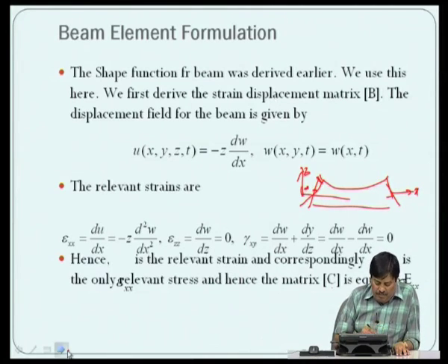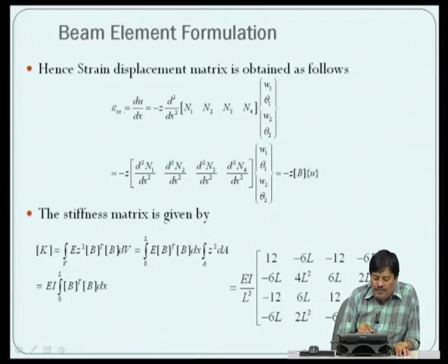Here we plug this back into this equation and derive the strain displacement matrix, which is du by dx, given there. When we substitute for u we get a second order matrix, and we substitute back into the governing differential equation and integrate between 0 and L, and we get this governing equation.